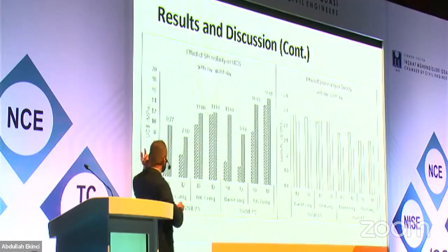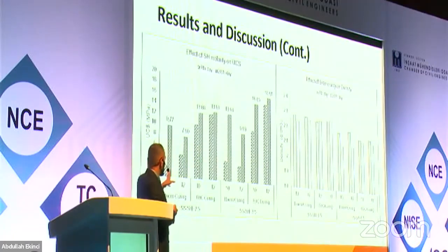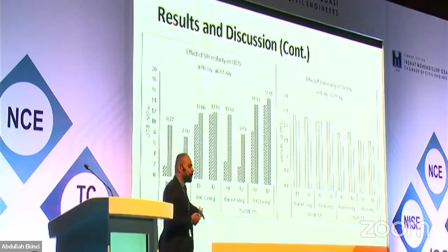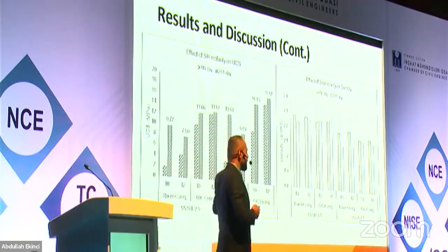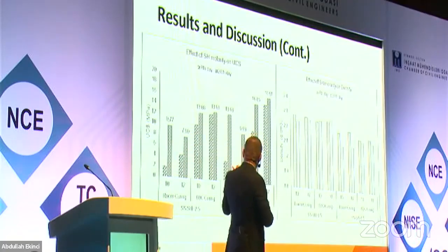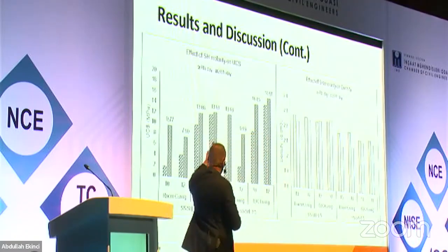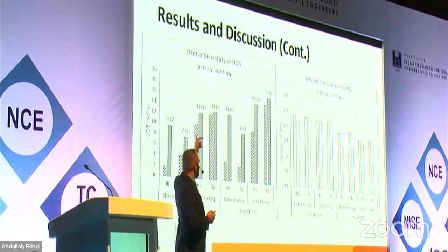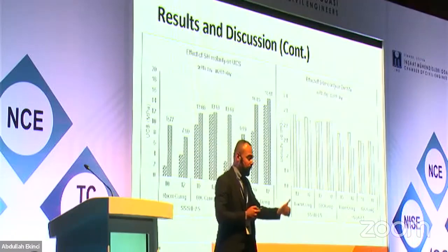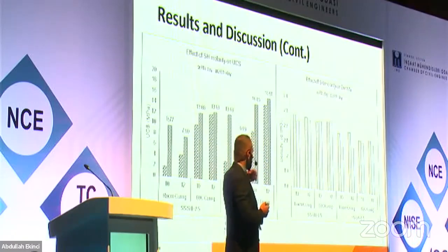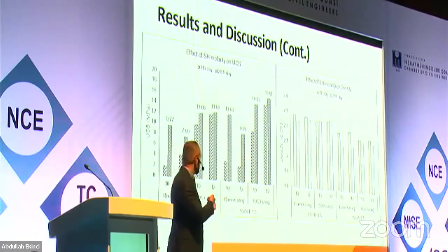So the things that we have with molarity is one of the aspects in geopolymerization that we tried here. It's clear that in most of the cases 10 molarity will be more than enough. In future research, we might even reduce this one because the glass already has high sodium inside, which may leach out and be used for the geopolymerization. This is one of the drawbacks in geopolymer because it's not a user-friendly material. On the other side, sodium silicate is a user-friendly material, but this is one of the drawbacks that we have. In future research, we can focus on alternatives or other ways to be used for activation.